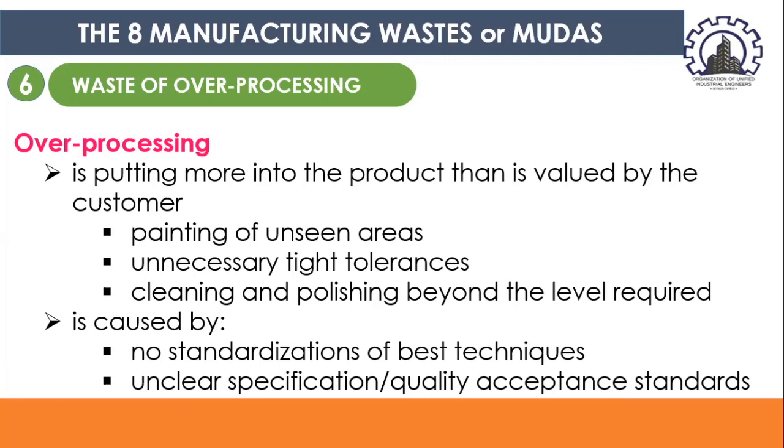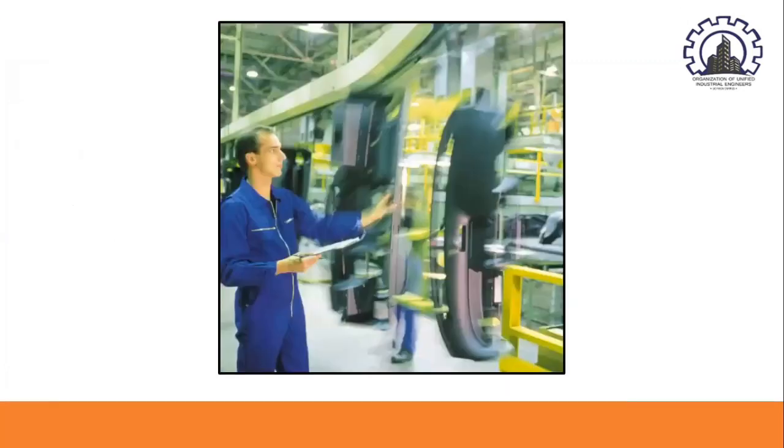So in lean, small is beautiful. Use small, appropriate machines where they are needed in the flow, not break the flow to route through a highly expensive monstrosity that the accountants insist is kept busy. So the goal is to do only the level of processing to match that which is useful and necessary. So this is an example of over processing. This is already unnecessary, and therefore we should eliminate or reduce this waste.